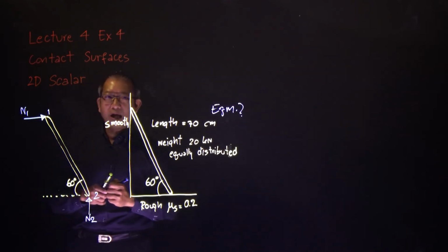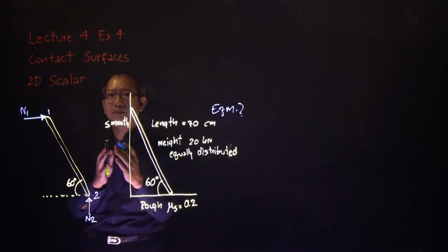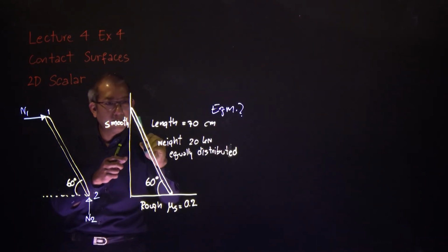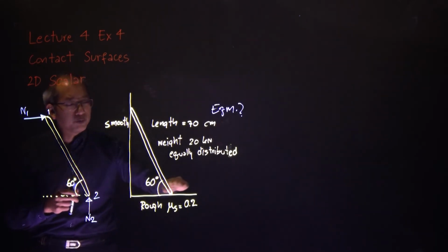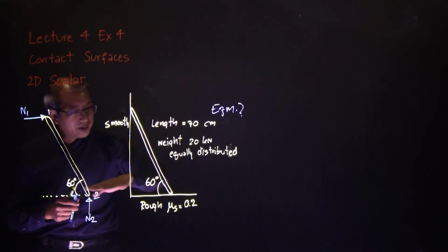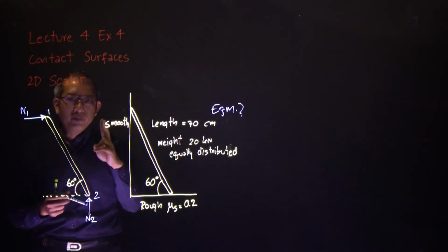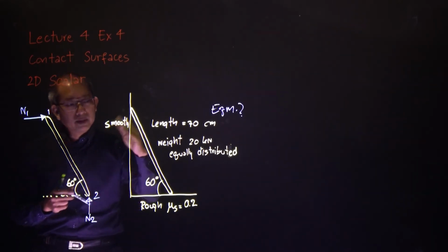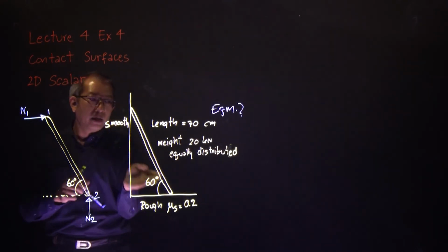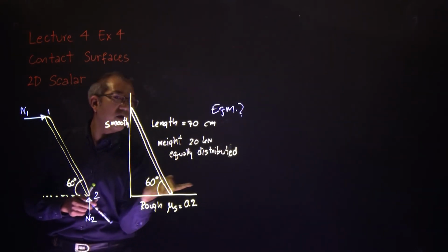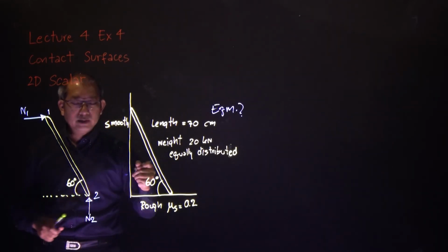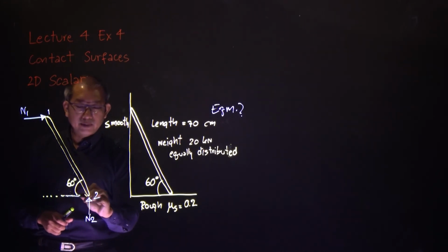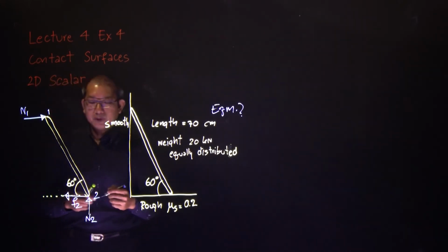Now, if we imagine, how would it move? How would this stick move? It would slide down this way and rotate like that, correct? Now, friction has two rules. One, it has to be parallel to the contact surface, so it's on this line, right? Two, it must resist the movement. If it's going to slide this way, meaning the bottom here is trying to slide to the right-hand side, therefore friction has to push back to the left-hand side. So in that case, it is this way. F2.